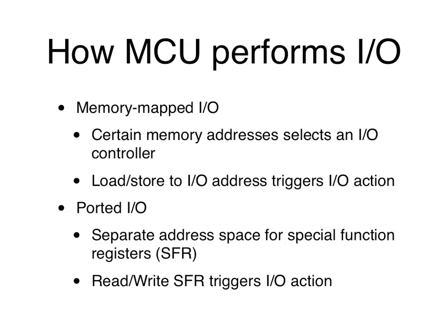Now, just because you can address a large enough space doesn't mean you actually have that much memory. Your actual memory can be less than the space you can address. Does that make sense? Just because you have a processor that uses a 32-bit address doesn't mean your computer has 4 gigabytes of memory. You could have 2 gigabytes, or 1 gigabyte or less.